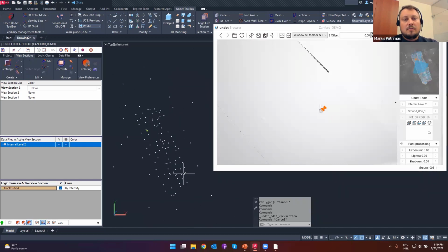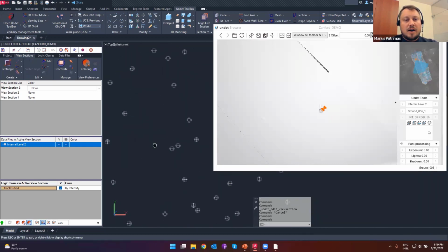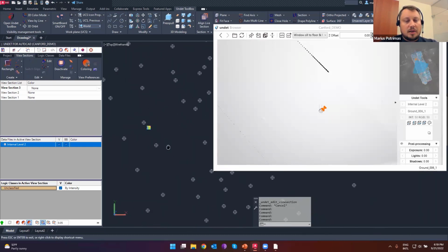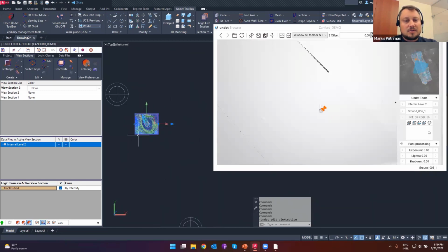So without this tool, you should find the small clipping box by clicking this. The software will show you where your clipping box is. So using Translate with Section feature, you can move your point cloud slice up and down.